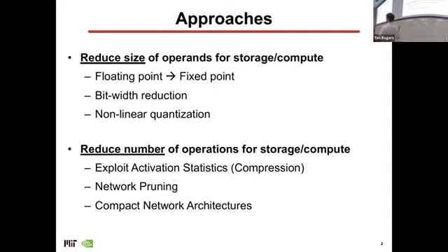And all the end developer cares about is how long does it take to converge, right? That's all they care about. They don't care about what the specific value is. Well, they do care if it's right, but the rightness is in the accuracy, which is just how accurate is it and how much does it converge. So system designers have exploited this, even in conventional GPUs and definitely in these bespoke accelerators, to play games with the precision. You don't need FP32, you don't even need FP16. In a lot of cases, you just need int4 or int8, and it still works reasonably well.